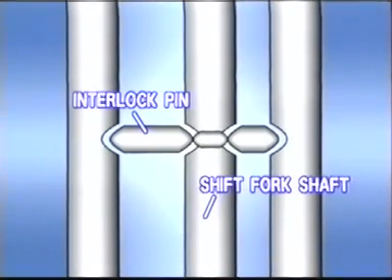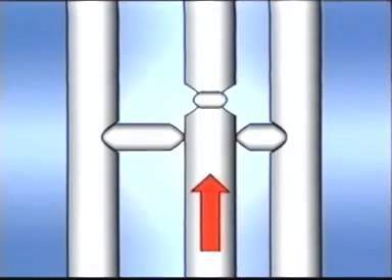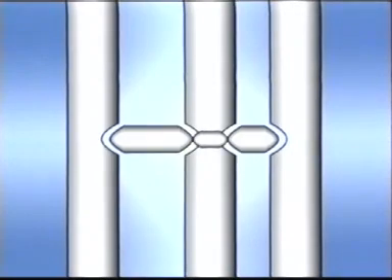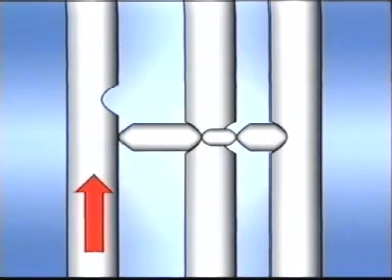With the neutral gear position, there is a gap between the central slot and the interlock pins. When the central shaft moves up, the two interlock pins are pushed out and inserted into the slots on both sides to lock. Similarly, when the shaft on either side moves up, the pushed interlock pins lock the other two shafts in position. This is how the double meshing prevention mechanism works in W58.